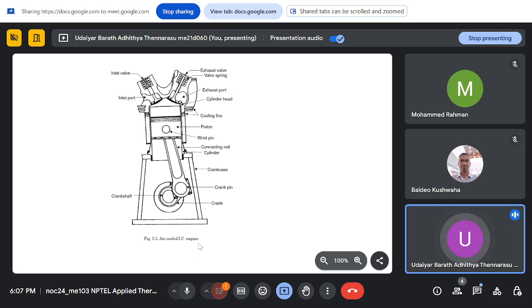So you have similar valves with different profiles, like an eccentric. You have different profiles on the shaft, which will sit over these ports and valves and just push the valves down. So that's the camshaft. The crankshaft is where you have the piston, which is connected through a connecting rod, and the connecting rod is connected to the crankshaft. Whatever power is generated in turn rotates the crankshaft, and you have the power delivered.